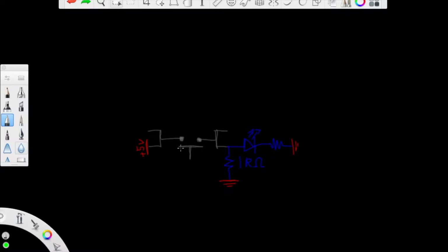And so this is the part that you push with the button. You push this down and it connects these two contacts. So you'll push it down like this, and then as soon as you let go, it will go back to normal. But when you press the button, there's a good chance that it can bounce off the contacts and then onto them, and then maybe bounce off and on a couple times.